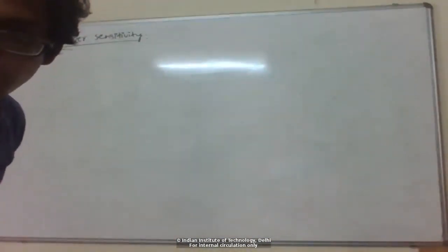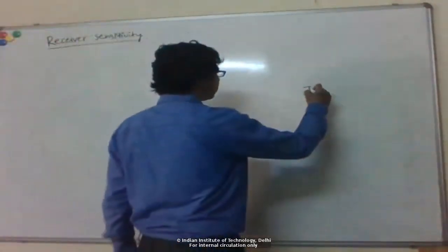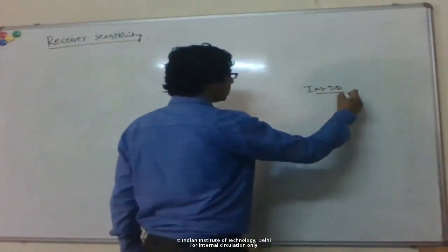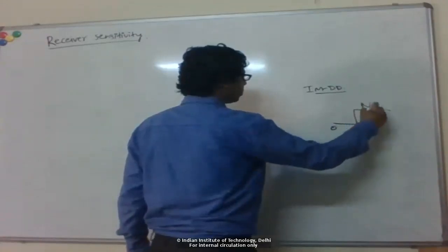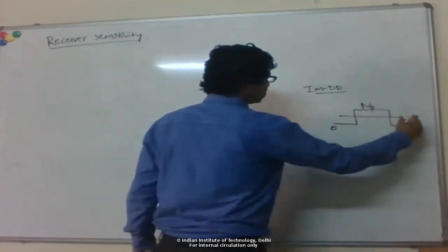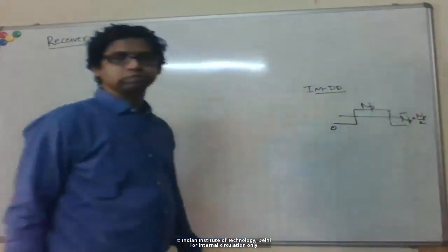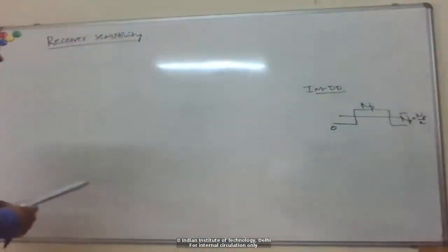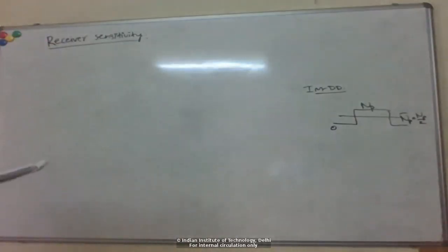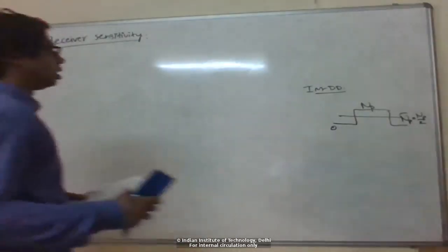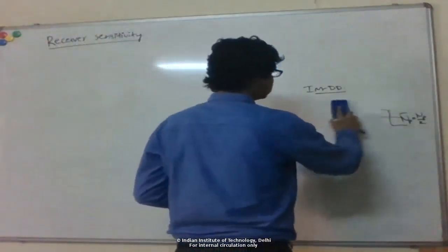So there's a question: how did you compute average NP? That was just a factor of 2. For an IMDD link, if I'm sending 0 photons for bit 0 and NP for bit 1, then my average is the number of photons for bit 1 divided by 2. I just use that, given that for a long string we have an equal number of ones and zeros.